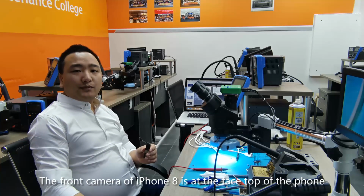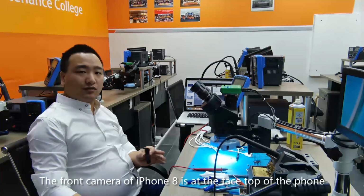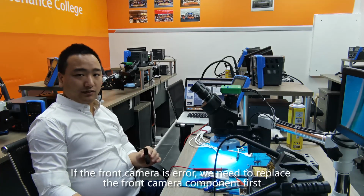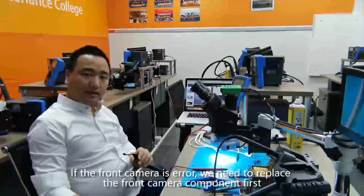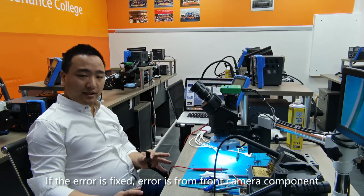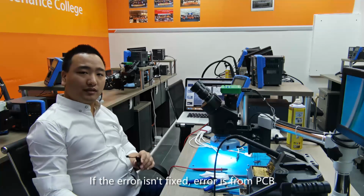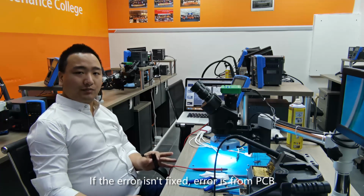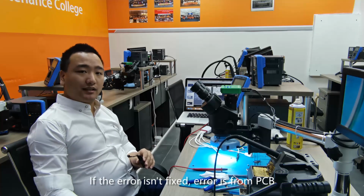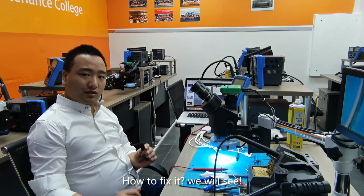The front camera of iPhone 8 is at the face top of the phone. If the front camera has an error, we need to replace the front camera component first. If the error is fixed, the error is from the front camera component. If the error isn't fixed, the error is from the PCB. How to fix it? We'll see.